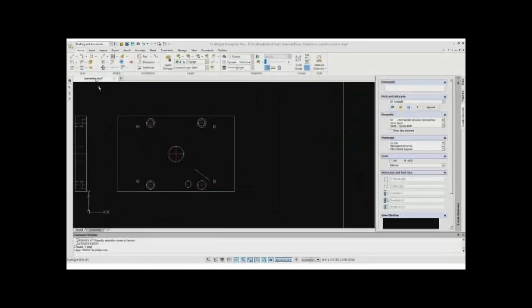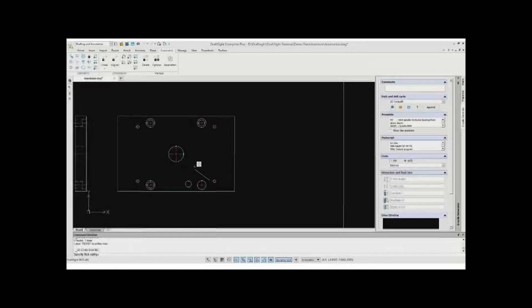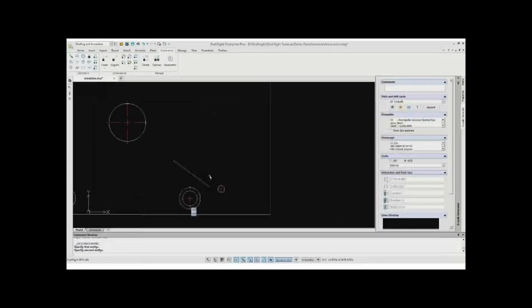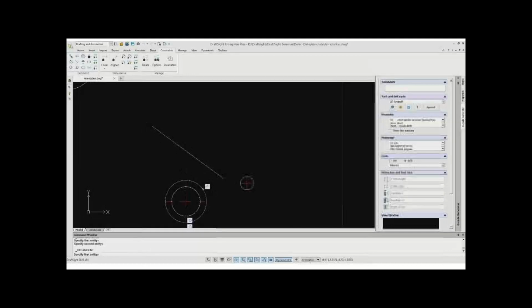And next we can see the constraint options. We all know that constraints are very important in creating drawings. If you're creating an entity, you have to constrain it. Why? Because if someone makes changes, the entity can otherwise collapse automatically. So each and every entity must be in a constrained state so that changes do not affect the developed drawing. And following that, we can discuss the view options.